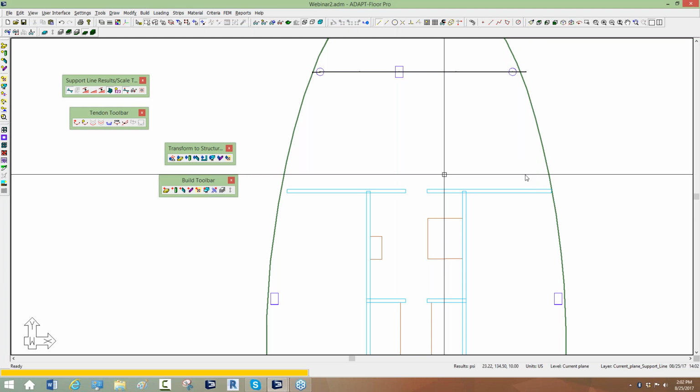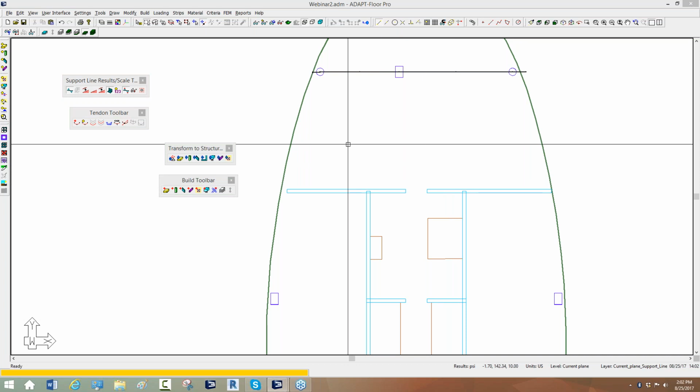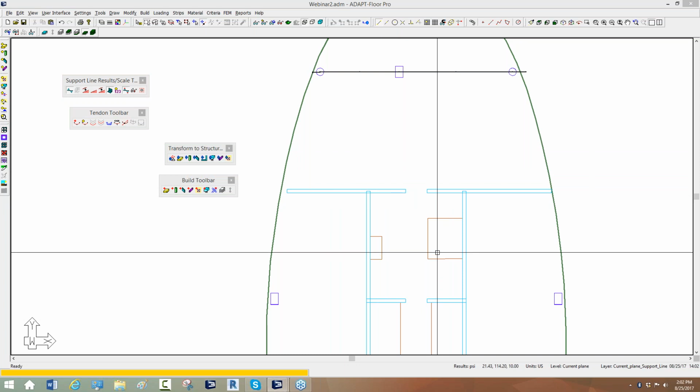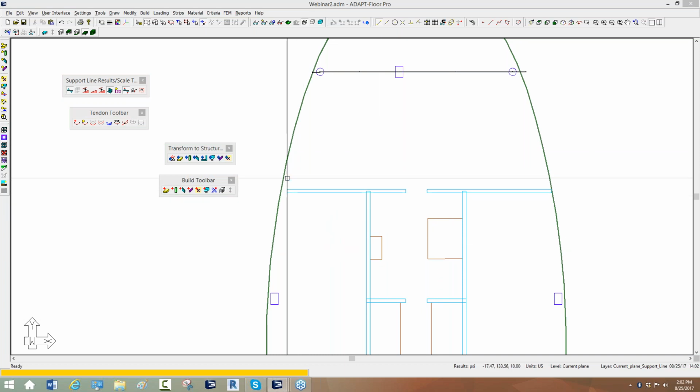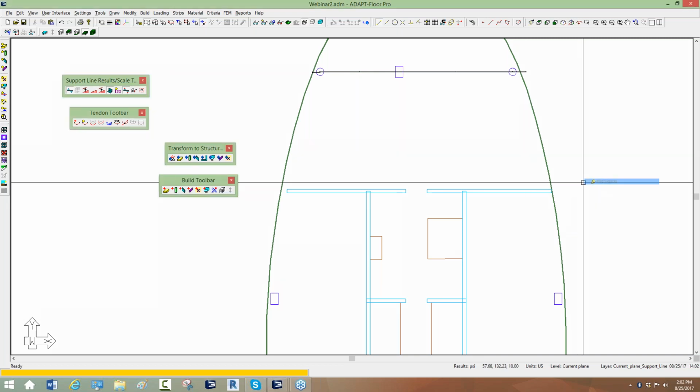Well, we don't need any drape in the tendons over the wall, but because it's a two-way PT slab, obviously if we have a continuous wall, then at and near the wall it actually starts to behave one way, but we're adding tendons here to pre-compress the slab over the wall. That's the only reason that we add the tendons, is just simply to provide pre-compression in a zone that might be, from here maybe out to here. In this zone, we want to add pre-compression to the slab in that particular region over walls. So we just run those straight through.